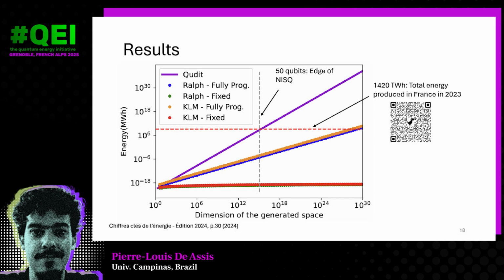That's why we went with electro-optical modulators, because for EOMs, this is a fixed cost: it doesn't really matter how fast you program your chip, that's the amount of energy you spend. But in the case of thermo-optical modulators, everything becomes a function of your time to solution, because the longer you need to run your gates, the longer you're leaving your resistors on, and the more power you dissipate. And the paradox is they need to cool the SNSPDs in the same circuit, so they need a very low temperature, but they have these heating circuits, so it's contradictory to some extent.